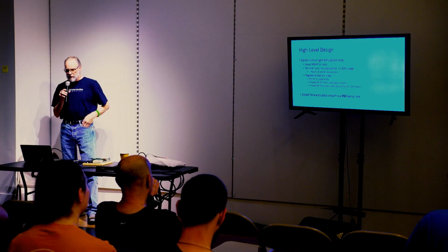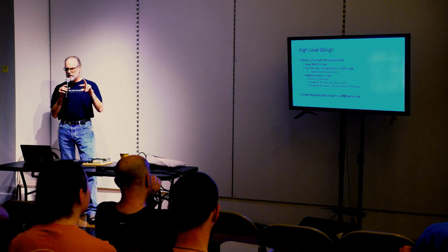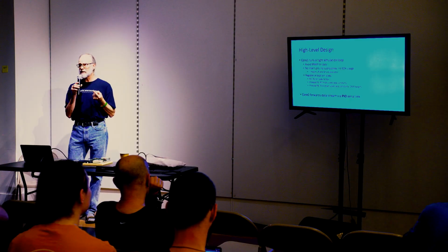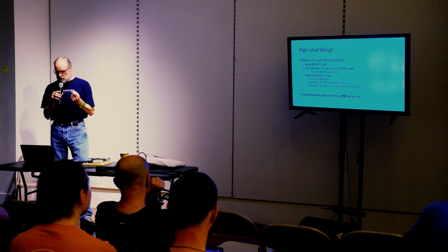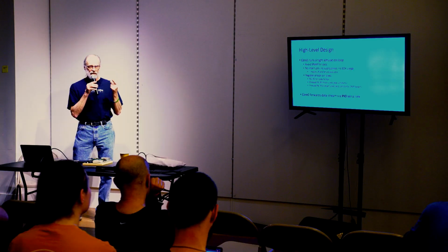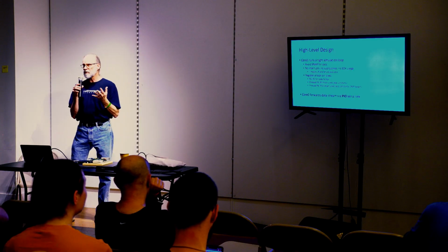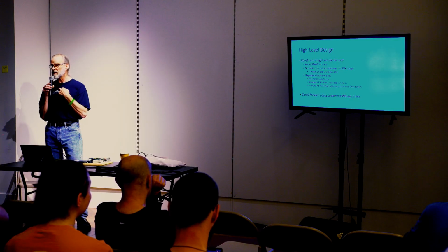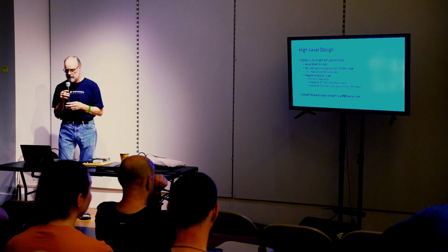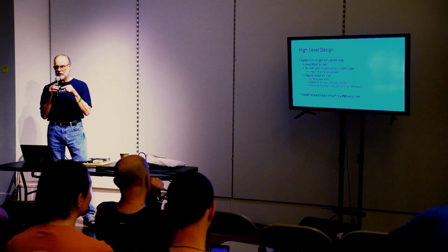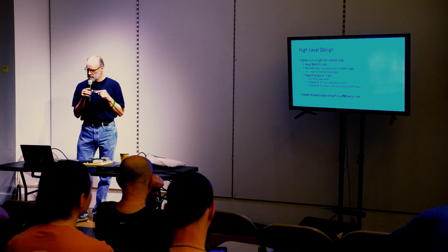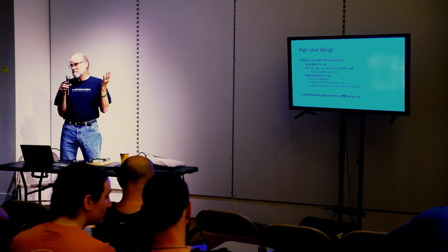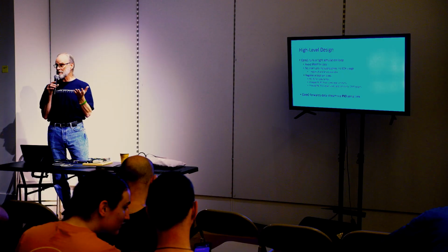So in this case, it's a dual core processor. Core 1 is going to run this tight emulation loop. It never touches SRAM unless it absolutely has to because touching SRAM is slow. There's no interrupts. There's no subroutines. I never call the SDK because you never know what it's going to do or what they may change behind your back. So basically, if it's executing an instruction, it's my instruction. It's one I'm asking it to do directly. But one cool part about no interrupts, subroutines, or SDK is that the link register and the stack pointer are fair game to use for whatever you want, because I can use the stack pointer. No one else is going to.